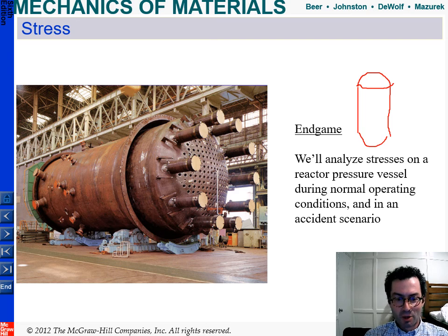What's going to happen? The pressures that are exerted upward, and I alluded to this earlier in the lecture, so you can go back and watch it if you feel like it. When we have a circular surface, you might think to yourself, do we use the total area in figuring out the stress? We don't. It's just the stress pointing straight up. So we're going to analyze the stress on this, and decide what bolts we're going to need to use to keep the pressure vessel head on the body of the pressure vessel in this situation.